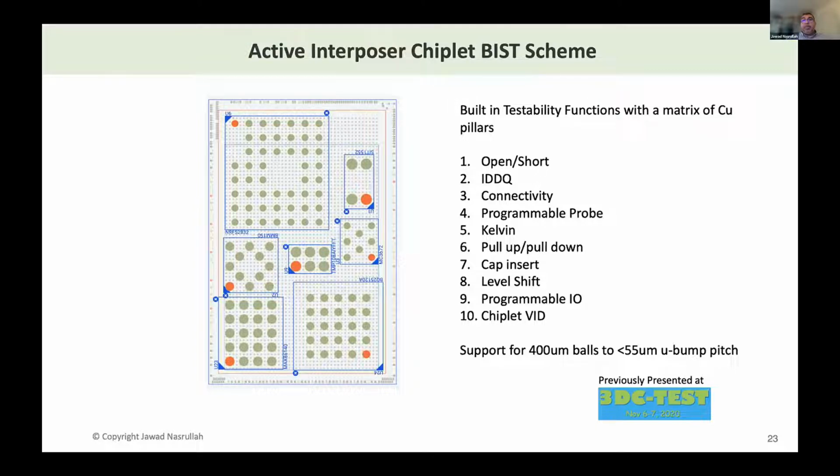And then we could actually inject a signal from one side on a trace that is totally unloaded and receive it on the other end. Not that we did that for every single one, but that was kind of the foundation of test development, at least in the system level test, as I call it. We did have programmable probes, so you would notice that around the silicon chip, there are sacrificial pads.